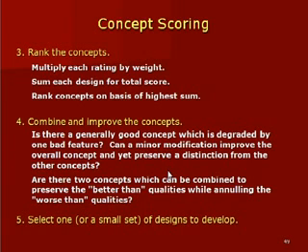And then the idea here is to use the rating and multiply the weight by the rating. So that's something we didn't do in the concept selection matrix. We treated each requirement as if they were the same. A plus is a plus, and all pluses are the same. Here, we're multiplying the rating by the weight to get a clearer picture and a more resolved view of which concept might actually be the best. Right? And again, we have the opportunity to combine and improve concepts.